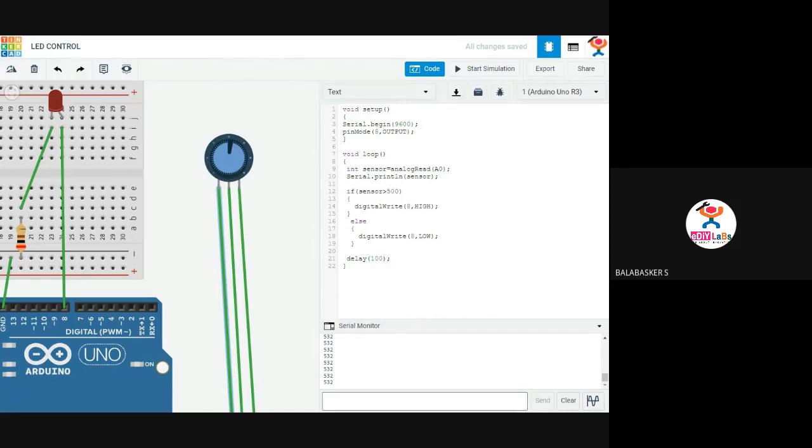Whenever you convert a value from digital to analog, the port available is an 8-bit port. So it is an 8-bit pin. 2 power 8 is 256. So whenever you are writing some value, you can write a maximum of 256 values, and since you start from 0, it's 255. So here, in the same program, I'm going to make only a small change. Right? Here, everything is okay.